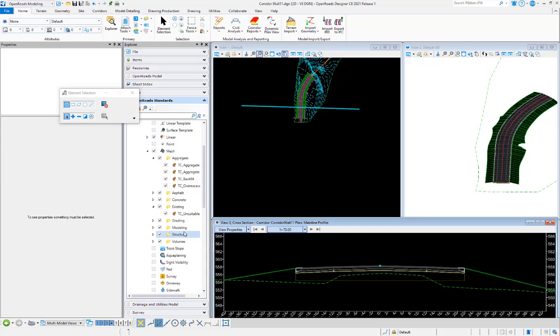In this video, we're going to talk about the custom volume option, which is used in what I call an over-excavation, where we need to prepare some bedding materials underneath, like a pavement structure. In this case, for example, we're underneath the pavement structure here, we're going down an additional 2 feet, and we're going to quantify what needs to be dug out of the existing ground.